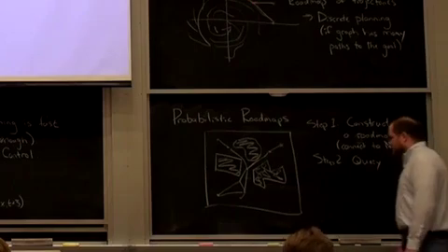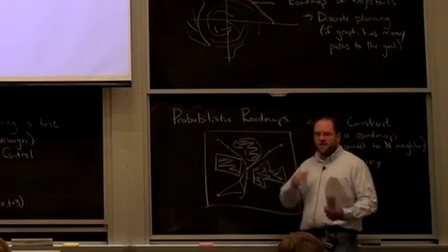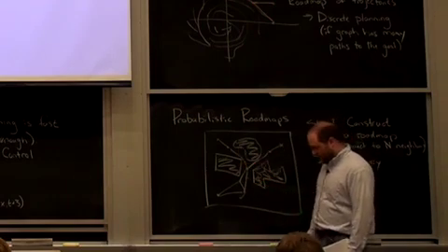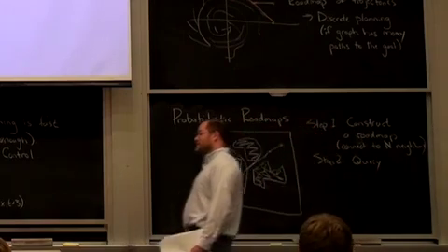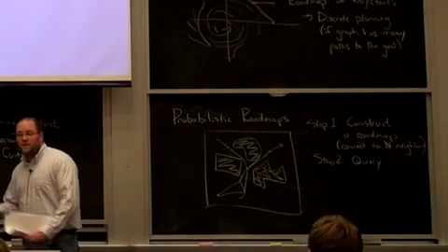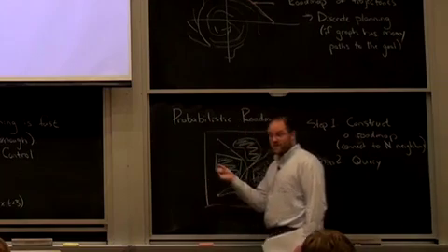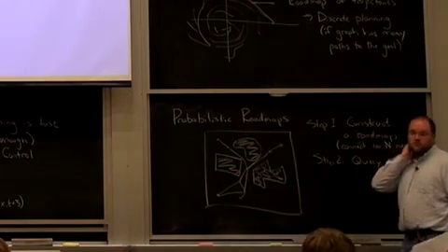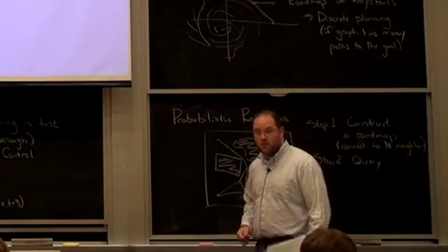You could almost think of this, in the dynamic sense, as having a bunch of repertoires, a bunch of things I know how to do, right? So maybe if it's a walking robot, maybe I know how to take a step here. That's one of my edges, I know how to execute that. I know how to take a big step. I know how to take a small step. It's a repertoire of local skills, right? Local trajectories in this case. And I just got to stitch them together in the right way. So that's a fairly robust thing.